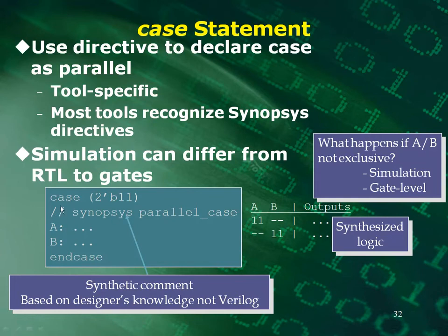You put your comment line, then synopsys, and then some information after it, like in this case parallel case. So if you're using the Synopsys tools, you're telling it that, hey, these are going to be mutually exclusive. I want you to generate your logic as though these two things are mutually exclusive. Then it would actually produce mutually exclusive type code.